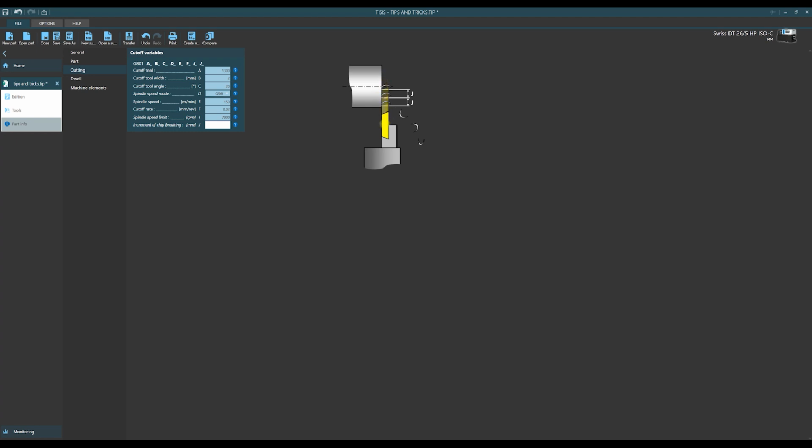It means that a tool moves by given distance, for instance 1 millimeter, and after it stops for a time given in second in the next parameter K. This stop is done to break a chip. And the last one, it is also possible for a tool to retract a little.